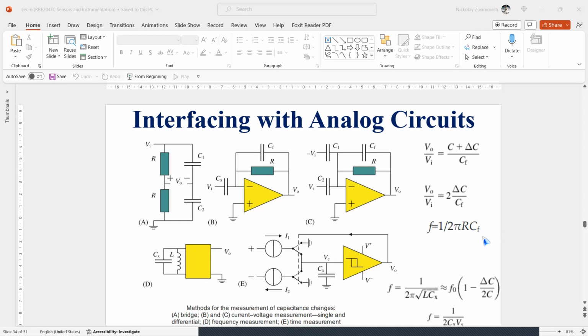The sensitivity is limited by the stability of the initial state, where the output should be zero. Neither the amplitude drift nor the frequency instability of the oscillator affects the zero stability, since they are common to both differential sensors.